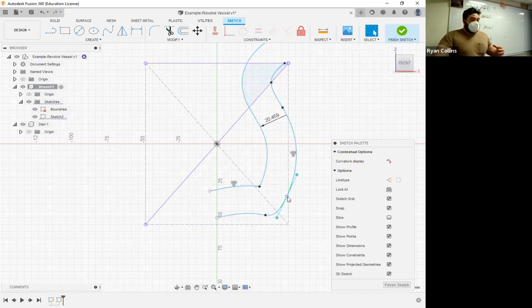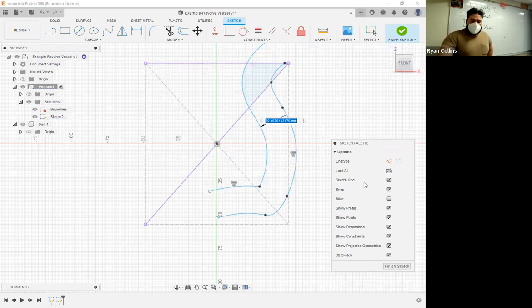So if you drew a second line by hand, you would have to redraw that one as well. Or the opposite, if you wanted to maintain an inner wall the exact same way and wanted to manipulate the outer one, then don't use an offset. Draw two separate lines. In this case, I'm going to use the offset because I want to do that. So I'm going to double click there again, bring that back to 3 millimeters. Good.